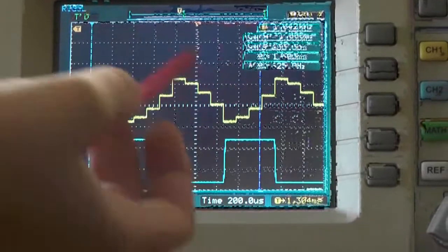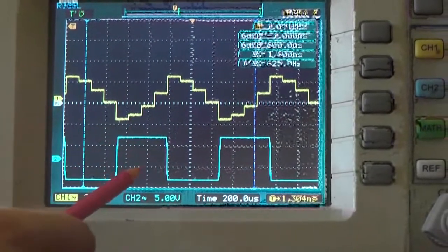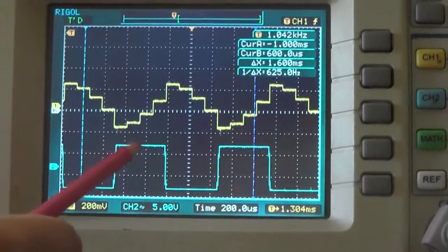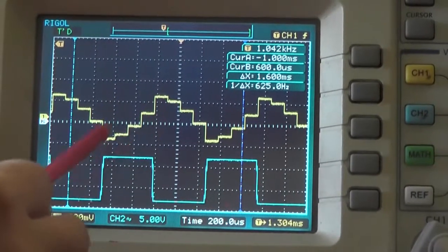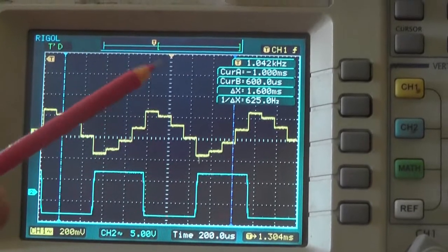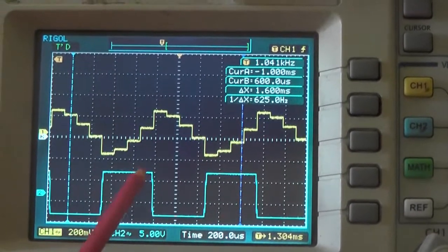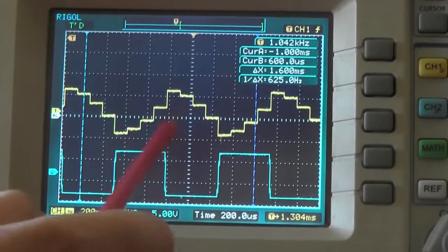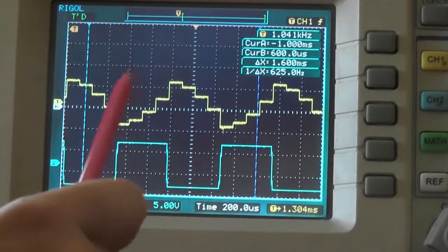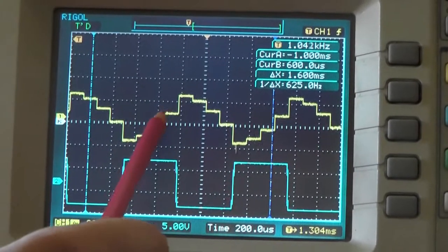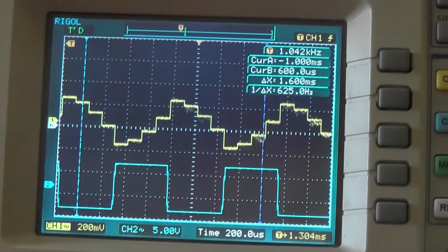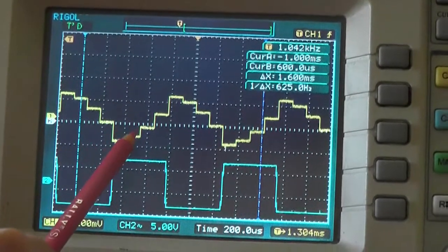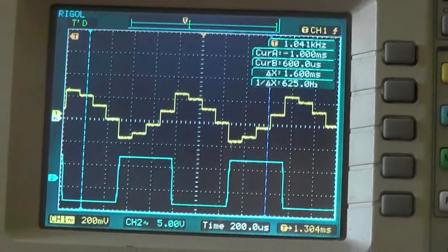As we can see, here the DAC output as well as the ADM output is shown. The DAC output is compared with the ADM output. The increasing step size of the DAC output corresponds to the +1 bit of the ADM output, whereas the decreasing step size corresponds to the 0 bit, and the step size is varying, that is non-uniform quantization occurs, and the step sizes are integer multiples of each other.